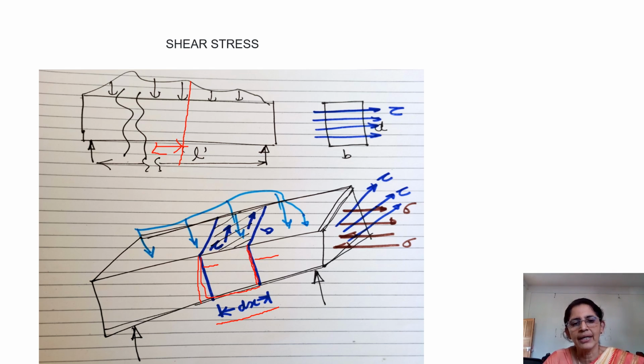That shear stress will be acting between the layers, that is shearing off. Understand? If you take this particular end, you can see that the shear stress will be acting between the layers to counteract this bending stress. Between these two sections, since there is an unbalanced bending stress coming, in order to counteract that, this shear stress will be developed. This is the shear stress which you are going to find out, how you can analyze the shear stress developed in that particular cross section. That is what you are going to deal with now.